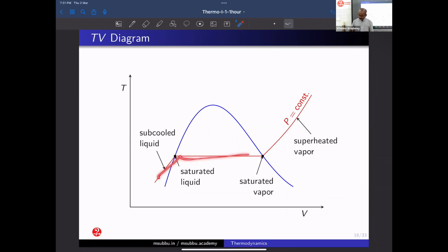So we'll be having pressure as a constant, and let us see how the diagram will look at constant pressure, say, the state of 1 bar. At 1 bar, initially water is at, say, 20 degrees Celsius. We are adding heat and the temperature goes to 100 degrees Celsius. At that point, we'll see the first vapor coming out. That is what is called a saturated liquid. And further addition of heat creates vapor in the relevant proportions.